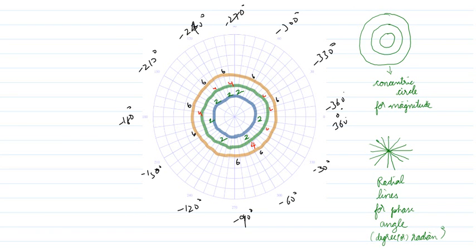Okay, right? And you can look at the number of divisions between these. You can equally divide the angle. This is minus 90, this is minus 120. The in between radial line should be 30 degree, so this should be around minus 105 degree, right? So the point you have to remember is the concentric circles indicate the magnitude which is evenly spaced. The lines which are coming out, called radial lines, are used to represent the angle. So if we are going to plot the magnitude and angle in this plot, this plot is called polar plot.